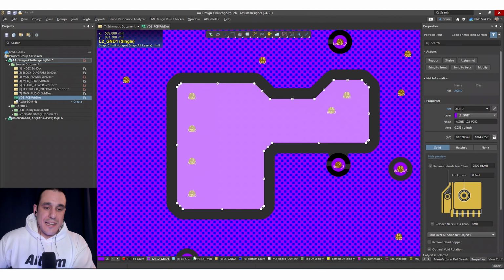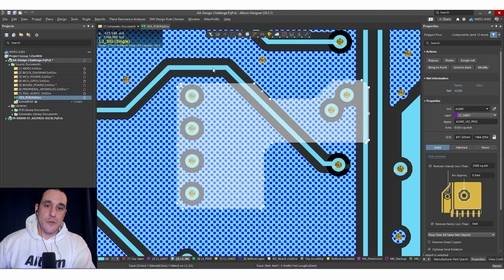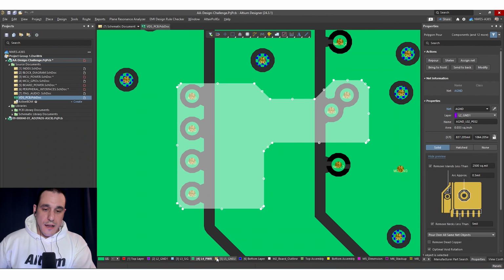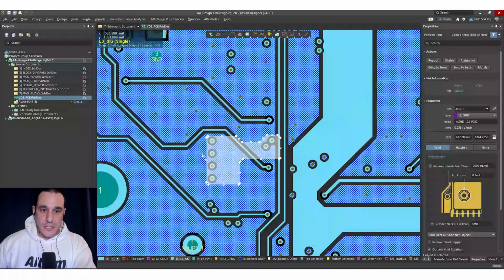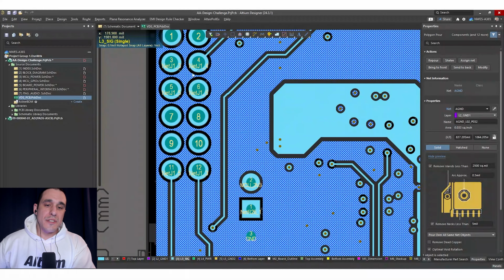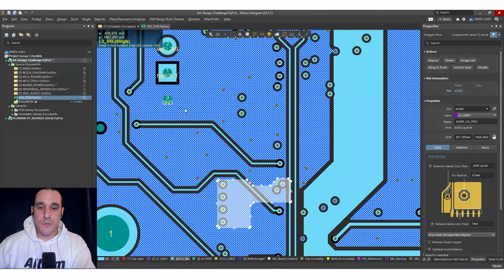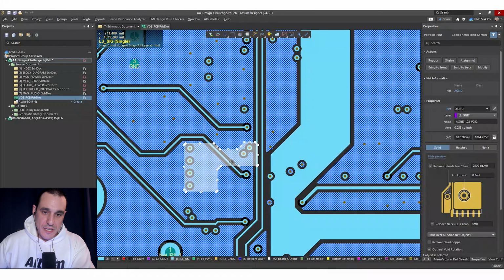So not terrible. I would prefer, if I were doing this, to take this trace and just route it down here, over and up. That would be the first thing I would change. This trace is also routing over these splits in the power plane as well. Then if we just take a look at what this trace is actually doing, we see that it's coming off of one of these connectors. So it could be carrying a signal. We don't know the speed of that signal.